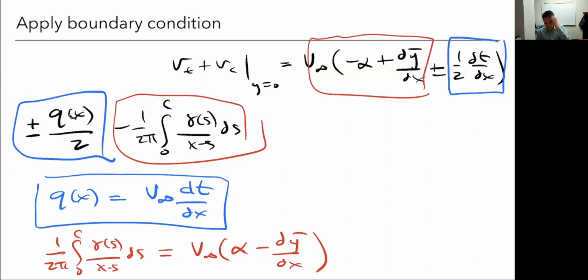So let's take it one step at a time. Let's do the easiest case, which is a symmetric airfoil. If it's symmetric, which of these terms goes away? Well, if it's symmetric, I have no camber by definition, right? So this term is 0. y bar is 0, right? It's symmetric, so the derivative of y bar is 0. So this is gone. So I'm going to bring the 2 pi over. I still have this term, but that's all.